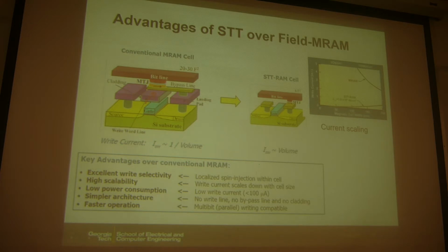As you scale the technology node, you get a smaller cross section for this red line, so you need to actually pass higher currents to generate the field, or let's say the current density will increase. So here, the current density will increase as you scale, because with the scaled wire, you need to pass more current to generate this surrounding field.